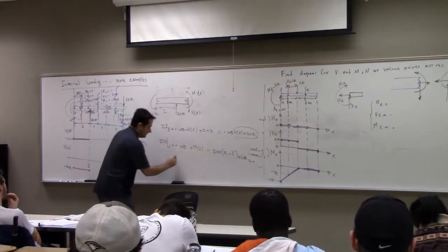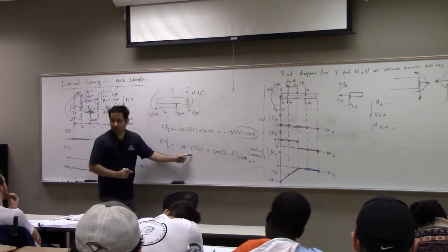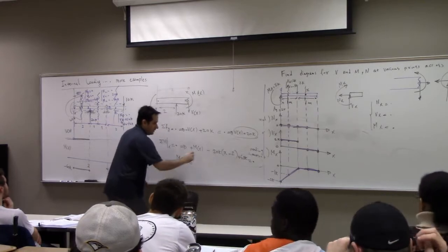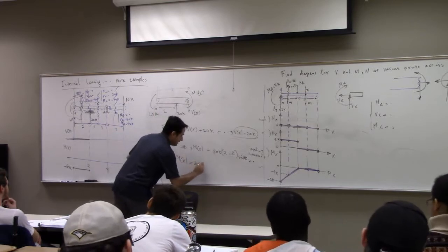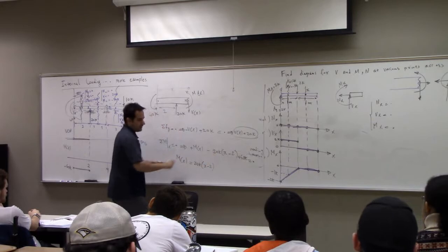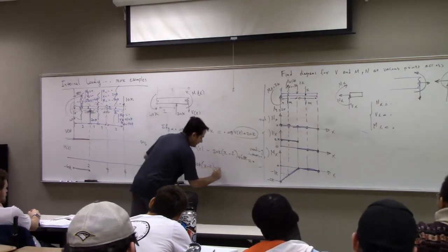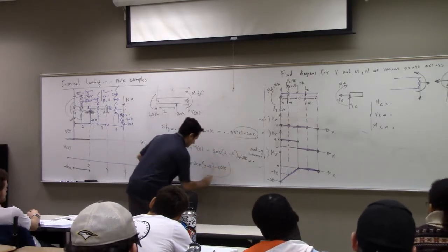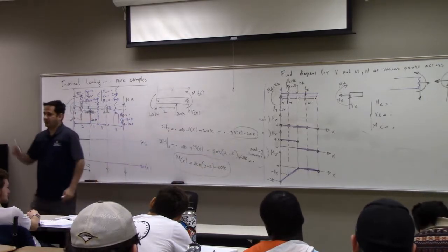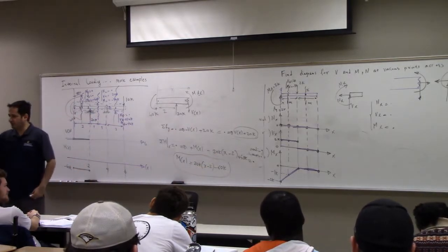What do you get? This is just the first time we do that. This is new. So mx, the bending moment at x becomes 20k. X minus 2, take this to the right, right? So you get 20k x minus 2 minus 60k. You can't simplify it more than this. Why? Because x is a range. X is not a number.